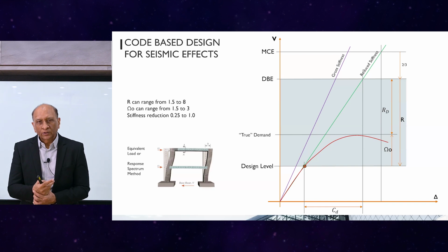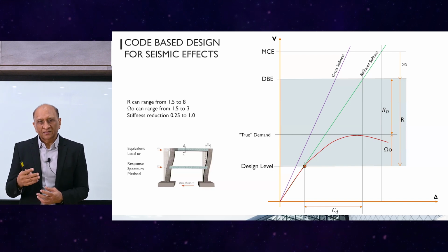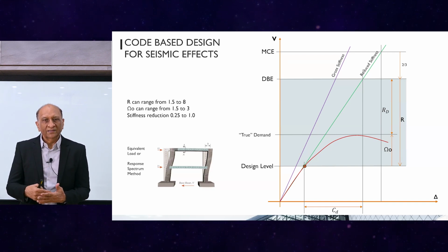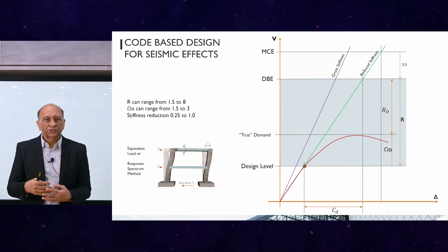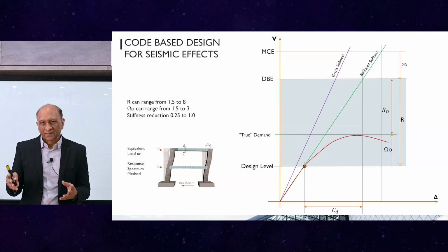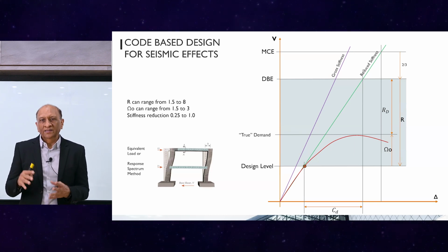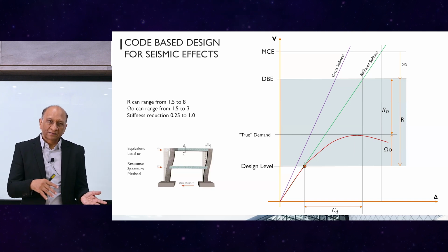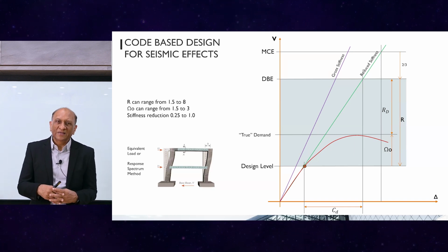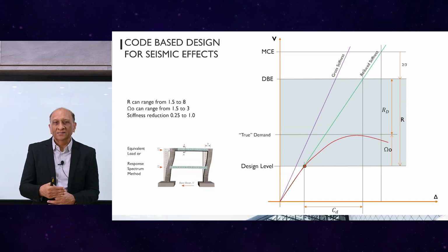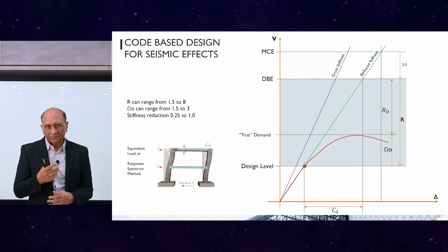So for R, we have three components coming from ductility, overstrength, and also from the period shift and damping effects and others. Some part of that is included in the R, some part we add externally as well. It's observed, done from research and testing, and I will show you one case where you can determine the R through analysis, roughly.